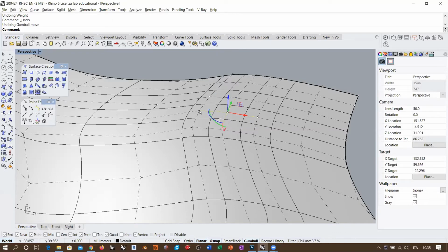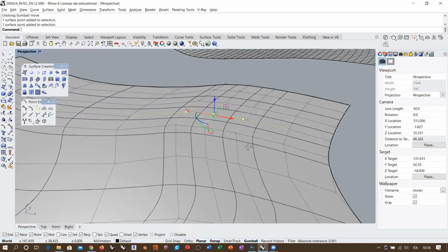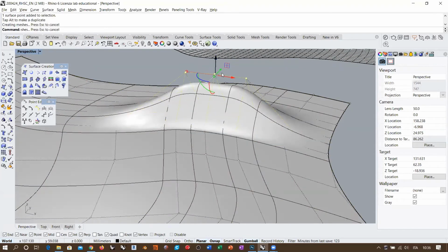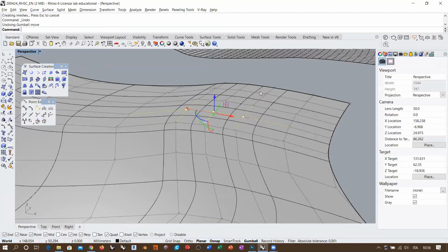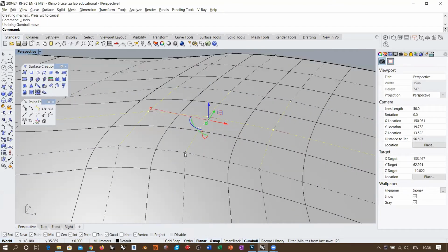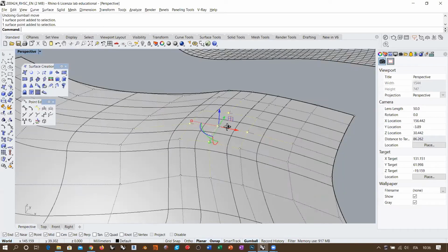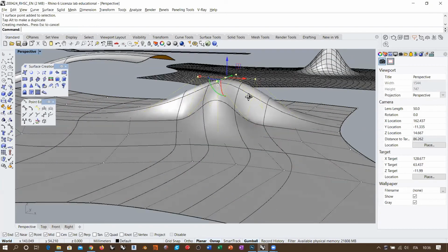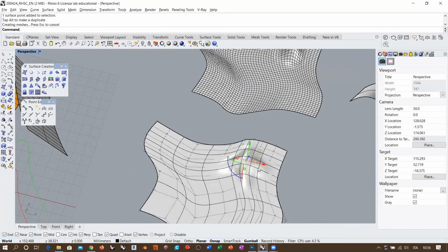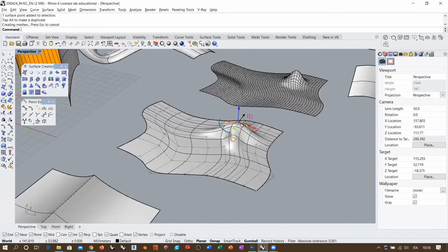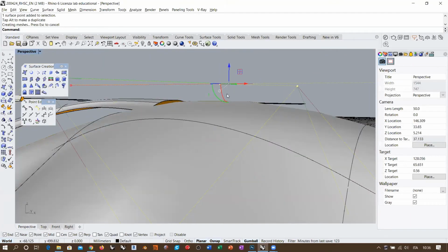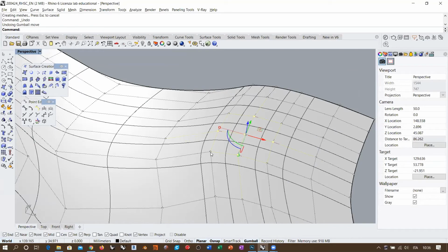So for example, if I take these two here and I move them all up, you see that I create this kind of situation here where the surface is still pulled up but doesn't reach this height. Why? Because the surface is a bidimensional domain. It not only works in one direction, it works in two directions at the same time. So in order to get to that height, I also need to consider this and this. And not only this and this, because I am not considering exactly the whole set of points. As you can see, you get this kind of nice cross here, but the surface doesn't reach exactly that height because I still miss these corner points.